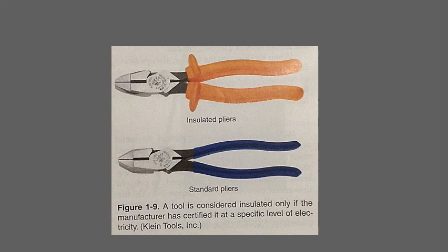Inspect the cords for damage regularly. If the insulation becomes damaged or the cord cut, do not splice it or wrap it with electrical tape. This is not a proper repair. Install a new cord to maintain the original safety of the tool.